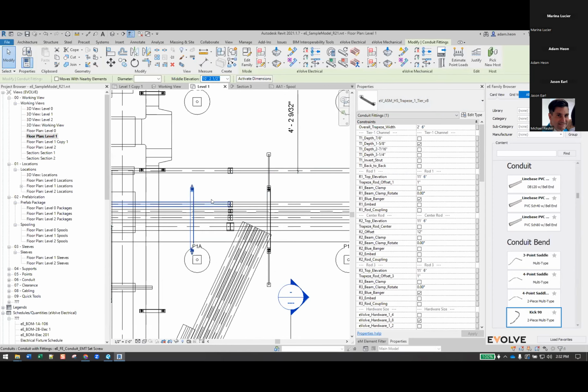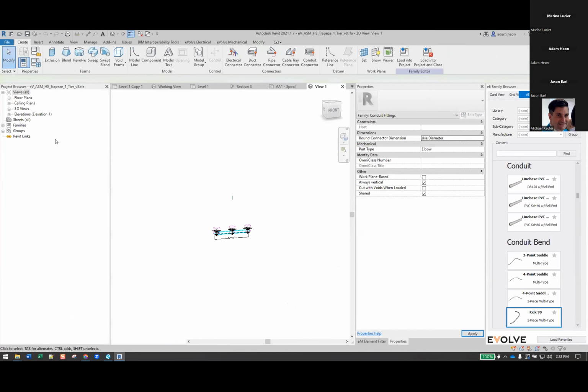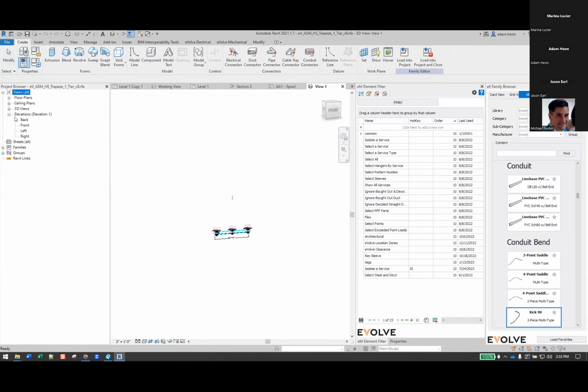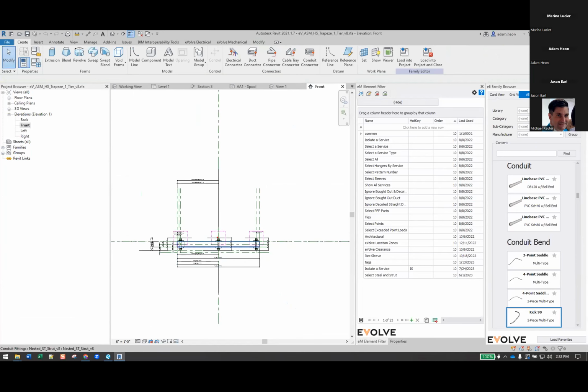But depending on how well you can modify families and figure this stuff out, the complexity is a little challenging. One thing, if you are going to try to make a family, what you want to pay attention to is the insertion point of the family. If you use our family as a proof of concept, the insertion point is there, top of strut, rods go up from there, width goes out, centered.